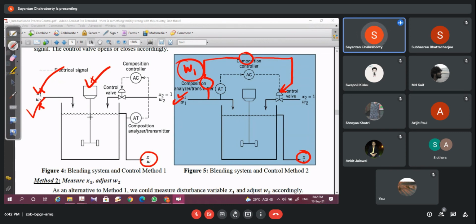Now, as we go on, we'll see that the plant model plays a very important role in the control system. If you recall, a feedback control system never requires a very accurate plant model. An abstraction of the plant model will be enough, because any discrepancy between the physical plant and the model can be taken care of by the feedback characteristics of the system. At the end of the day, it will make the control variable follow the desired value. Whatever model you start with, it has the capability of correcting for any error in the loop. That is the beauty of a feedback control system.